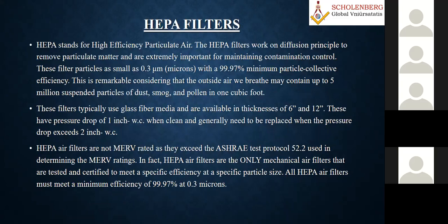Similarly, when it comes to the HEPA filters, diffusion principle, as I explained to you, this is also the final stage where it removes particles as small as possible. And this always uses glass fiber media, and because of the thickness there will be a high pressure drop. And HEPA filters are not MERV rated as they exceed the test protocol used in this.